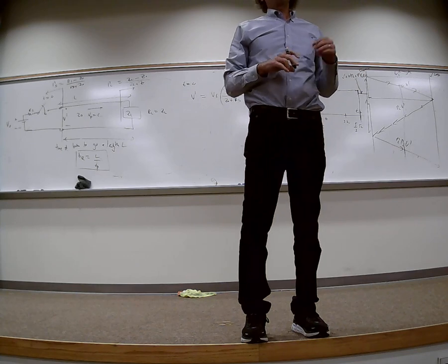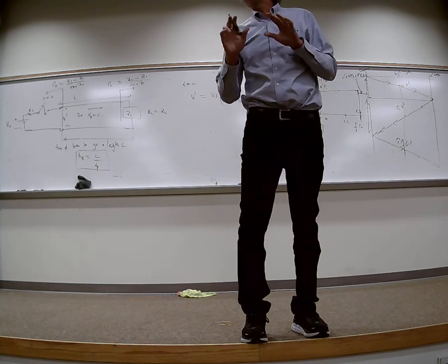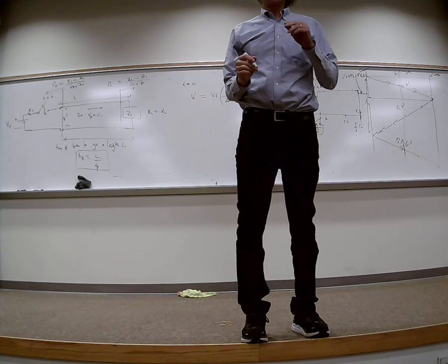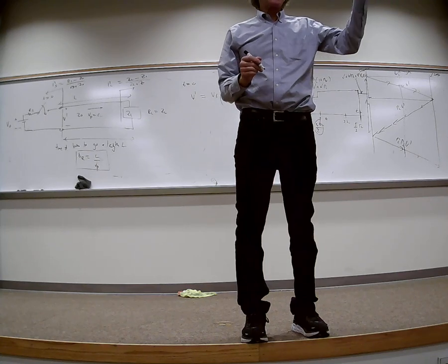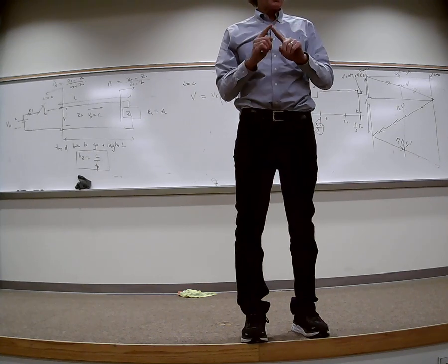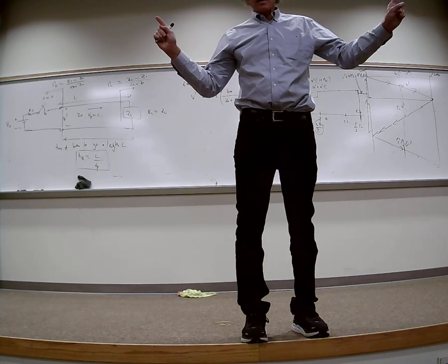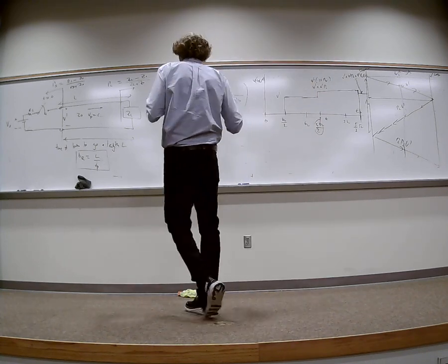Now there's one thing that's very interesting that I'm going to share with you. And we'll do several of these things so you get a good feel for it. It isn't hard. Just keep in your mind to always get the right value of the reflection coefficient to load, reflection coefficient to source, the time it takes to get down there, and then accurately draw this bounce diagram, all right? So here's the one thing. As time goes to infinity,